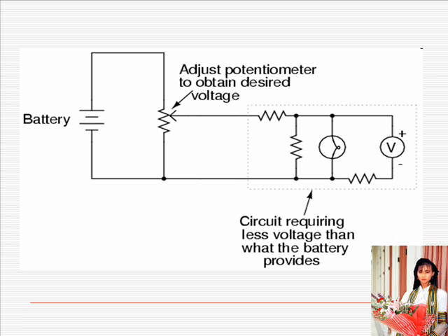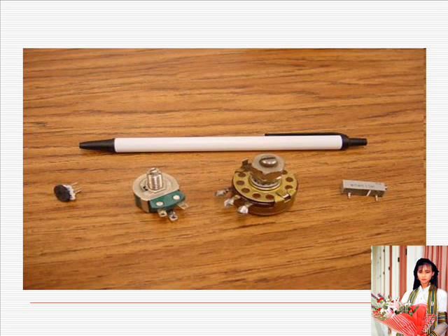When used in this manner, the name potentiometer makes perfect sense. They meter control the potential voltage applied across them by creating a variable voltage divider ratio. This use of the three-terminal potentiometer as a variable voltage divider is very popular in circuit design.